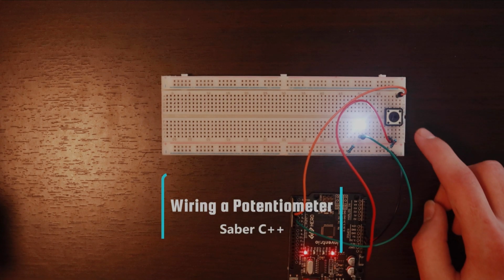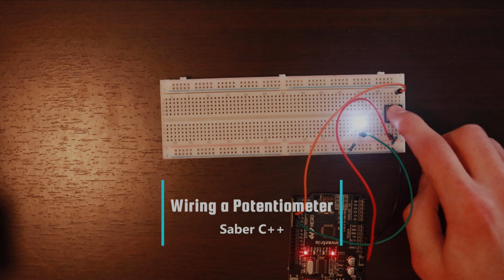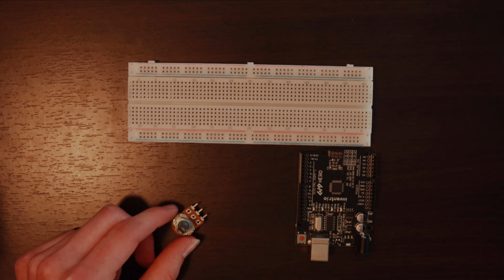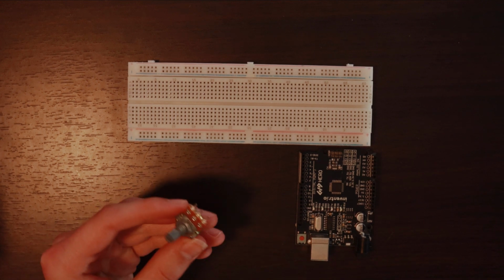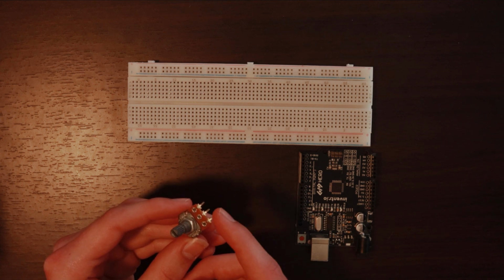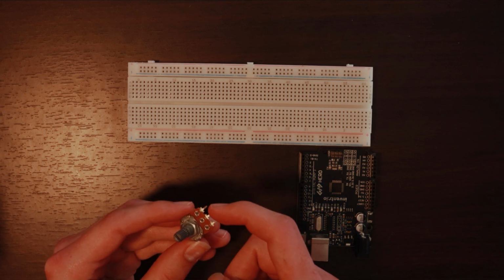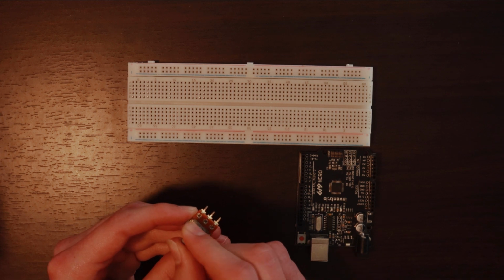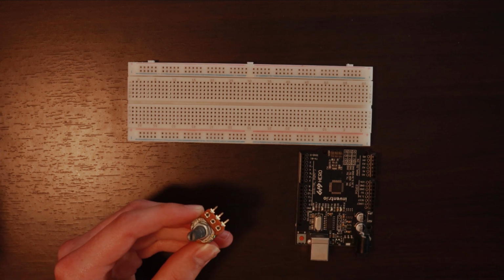And there we go. Now we can toggle our LED on and off with our button. Let's take a look at using potentiometers with our Arduino board. This is a potentiometer. We're going to supply power to it on the rightmost or bottommost pin, and then read the value from the middle pin, which will tell us how the dial is rotated and allow us to change the brightness of an LED.